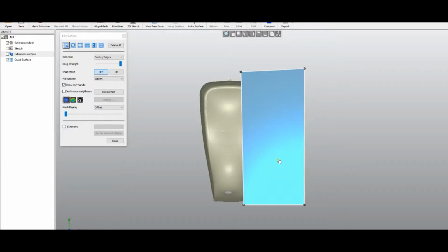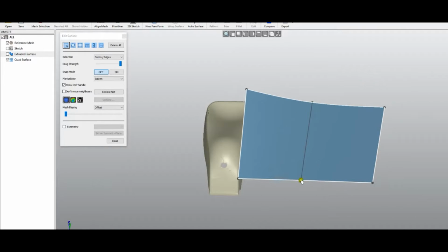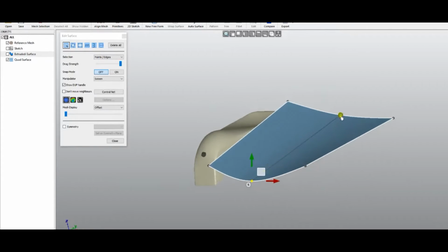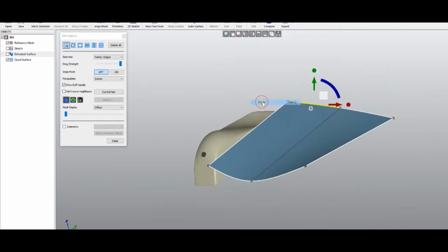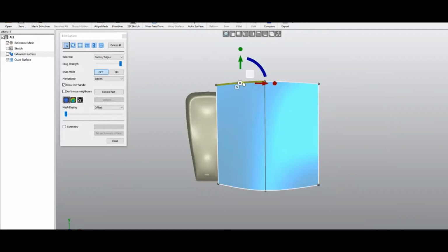So once we have this small rectangle, we can start building our surface. If I highlight an edge, you can see a small D sign here, which means that if I hold my left mouse button, it will duplicate my edge. In such a way we increase another edge here and we extended this surface. Then I can take this point and move it down and build this. For example, if I duplicate here, I'll just undo this because we're not ready yet from the top view.